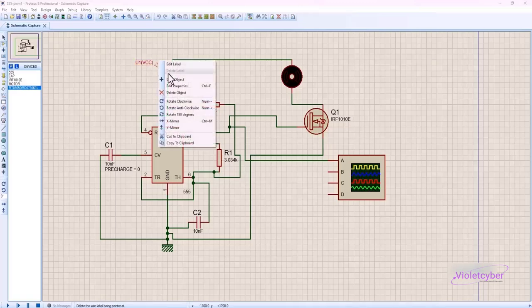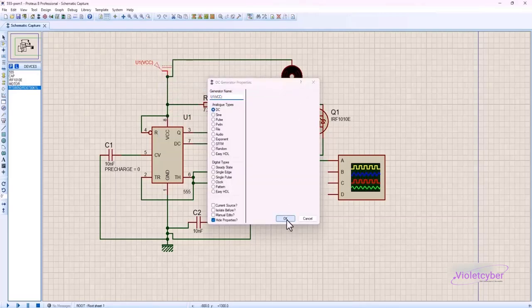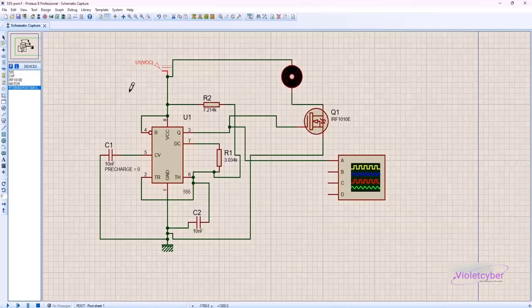I also assumed the operating voltage of our circuit to be 12 volts here, because the 555 IC can easily work with 12 volts. The only problem is that when you close the circuit like this and simulate it to get output, you might run into an error. This error in Proteus occurs because, when the 555 IC works, it is placed in a standard, isolated mode, and we have to take these capacitors out of the standard mode and into an environment mode.